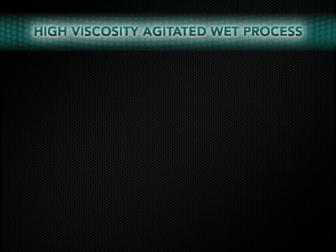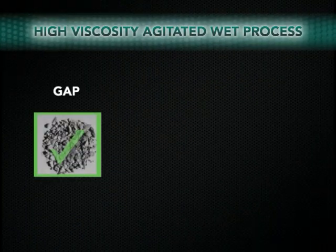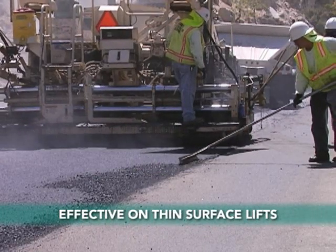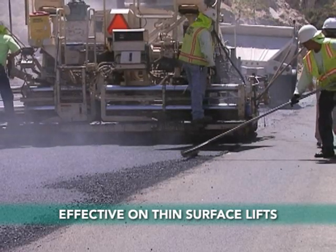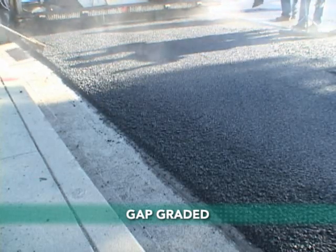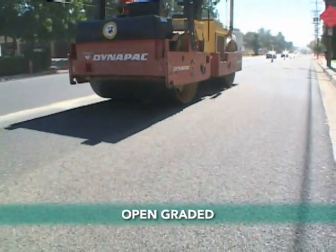The high-viscosity agitated wet process uses the largest amount of rubber tires and is most effective in gap-graded and open-mix designs. It is not suitable for dense graded mixes. It is also most effective when used on relatively thin surface lifts. Gap-graded mixes are used as a structural layer equivalent to conventional dense graded hot mix asphalt. Open-graded mixes are used in surface friction courses.